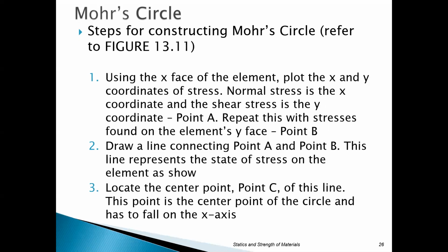Okay, so the first thing you're going to do is you're going to be given an element, and it's going to show you normal forces and it's going to show you shear forces. So you basically take those and develop the coordinates. So using the x face of the element, you're going to plot the x and the y coordinates of stress. Your normal stress is the x coordinate and your shear stress is the y coordinate.